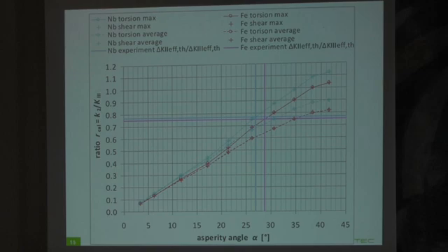So in this case, when they meet the dependence on the angle, they show us that in this area between 25 and 30 degrees should be the averaged angle of the asperities on the pre-crack front. So it means that the local mode 2 mechanism is possible to operate for already relatively small angles, 25 to 30 degrees.